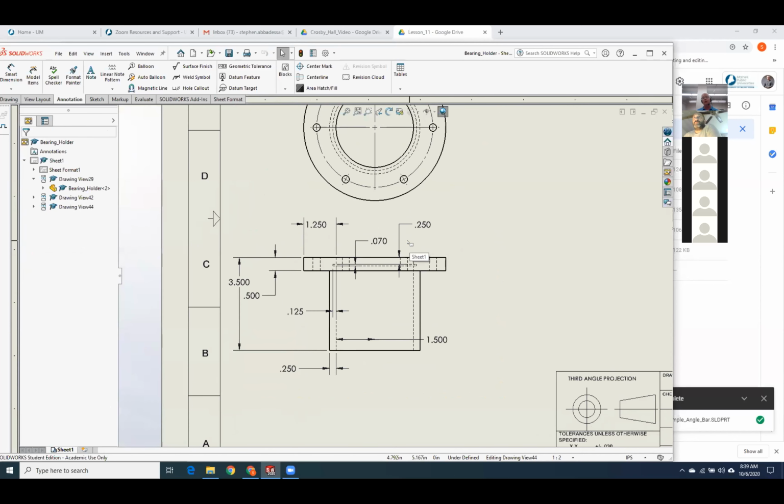So if you think ahead as you're creating your sketches, to which views you're going to put on the paper, you can do a lot of your drafting right from the sketches by turning on the design annotations. If you bring in the design annotations, it's bidirectional. If you just do smart dimensions, then you're just dimensioning what's on the paper, and it's not bidirectional. Okay?